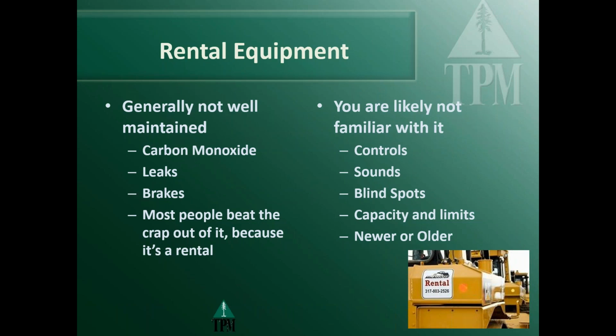So, rental equipment. It's not that I have anything against rental equipment. It's just that it's generally not well maintained. It has in all likelihood been beaten up by people because it is a rental. That may mean the brakes are bad or there are leaks. And this has happened multiple times, where a piece of equipment is putting out a huge amount of carbon monoxide, far more than what is allowable, because it's not maintained and not adjusted properly. So it's burning way too much fuel and generating a ton of carbon monoxide and carbon dioxide. Whenever we have rentals, we need to plan that the exhaust is going to be worse than what we are used to.